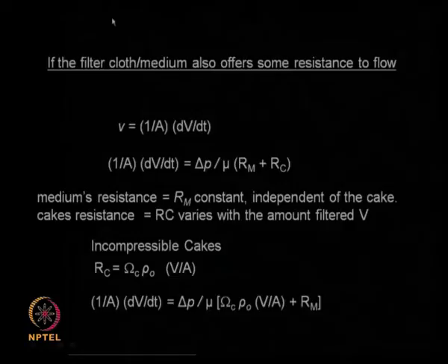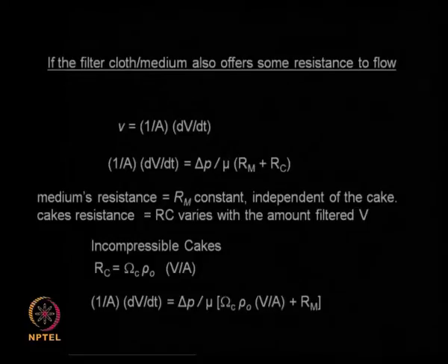So in such a situation, the Darcy's law equation is going to be different, and the resistance offered by the cake also will appear along with the resistance offered by the filter cloth or the filter medium. Both the resistances are going to appear in your Darcy's law relationship. So let us look at it again.